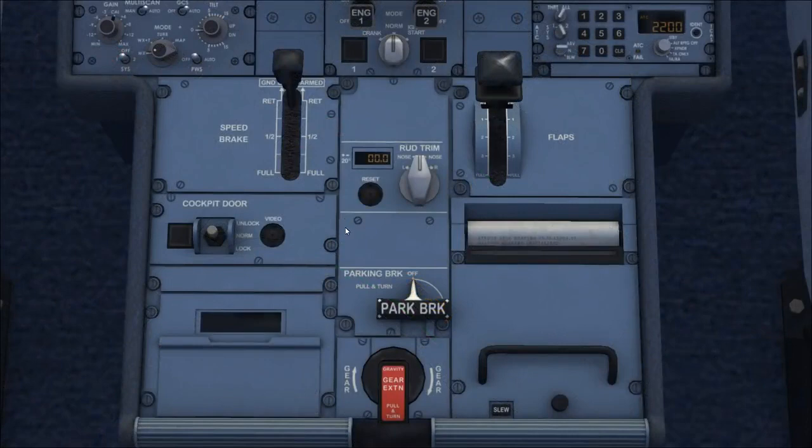Okay, and then finally at the back of the centre pedestal we've got several more controls here. The first on the left hand side are your speed brakes. So if you want to arm them, you can right click and it just pops them up into the top of the motion there, or you can click and drag to move the speed brakes back and forth. Same with the flaps, you can move them to position 1, 2, 3, 4, which is full, or up to 0. You notice in an Airbus the flaps don't have a particular number of degrees of extension. It's simply position 1, position 2, position 3 and position 4.